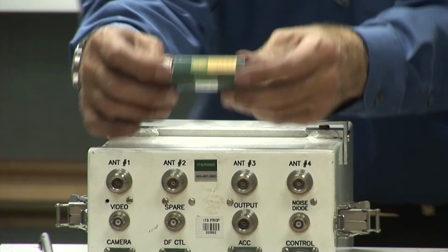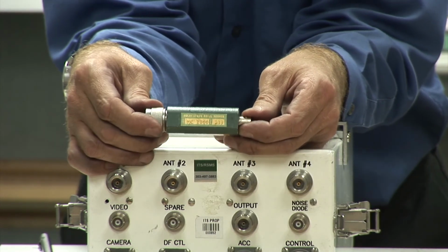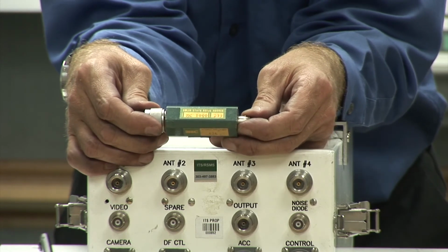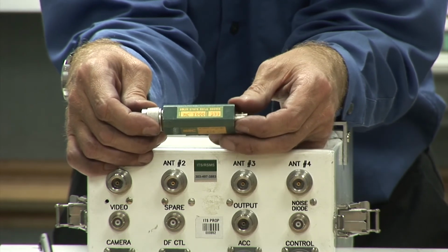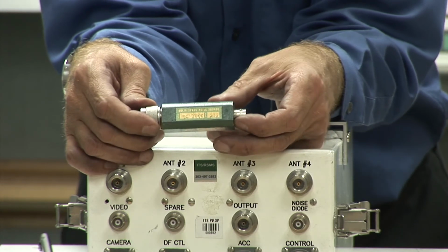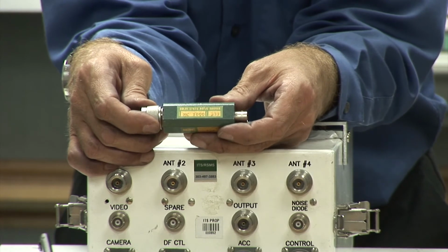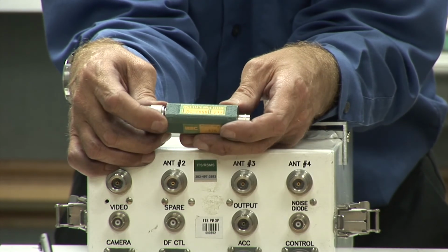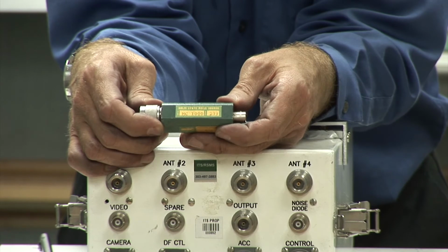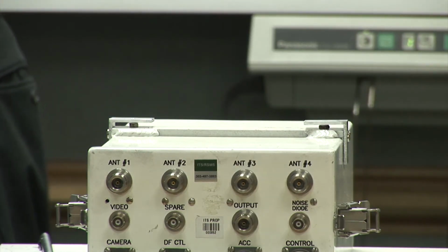We like to put a calibration source in. We haven't talked about noise diodes. We'll talk about those in a later talk. But this is a noise diode. This is a calibration source. And we like to put this into our front end also so that we can switch to it automatically, turn it on, look at the noise, verify that we have a path through our measurement system that works, and also get the actual gain and noise figure of our system at the frequencies at which we're going to measure, all with the noise diode.